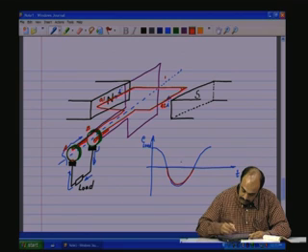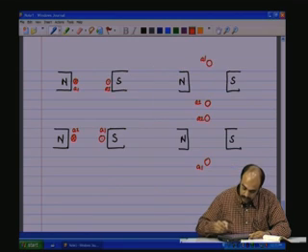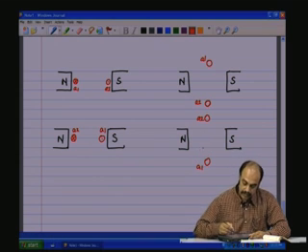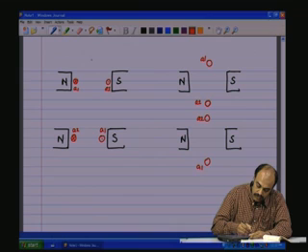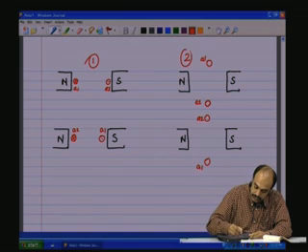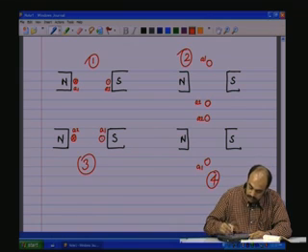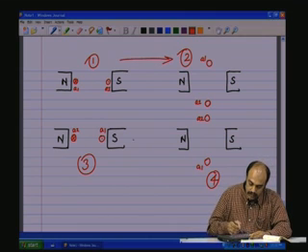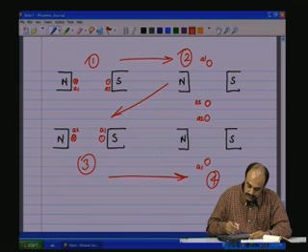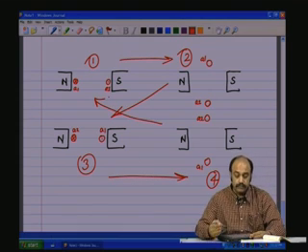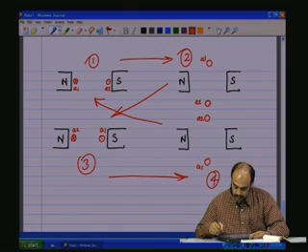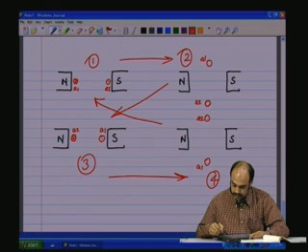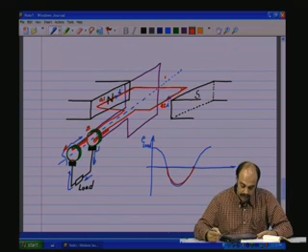And when it comes again to this point, it again becomes 0, no current flow in any of the coil sides, and then from here it shifts here. So, this is position 1, position 2, position 3, position 4, and then back again to position 1, 2, 3, 4, and so on. It keeps flowing in this fashion. So, these are the various positions, the four important positions in the motor in this particular equipment.